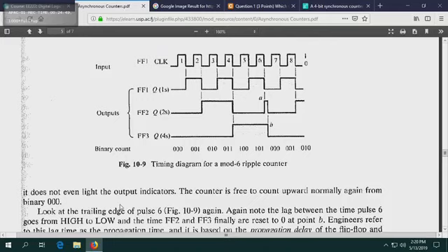Okay, that's the next timing diagram. Can you see it counts from 0? How do we know the 0? It counts 0, 0, 0. Then it counts 1, 0, 0, 1. Can you see flip-flop 3 is the least significant. Flip-flop 2 is the middle one. Flip-flop 1 is the most significant. Look at the second clock pulse. One clock pulse is one low and one high. Now, the third clock pulse, it's 0, 1, 0.